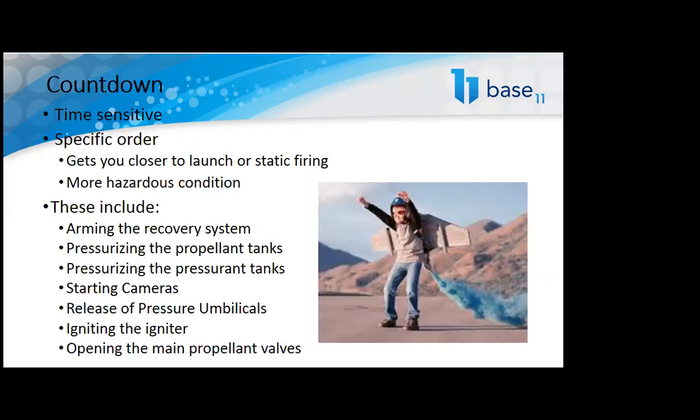You've loaded the propellants. You've loaded liquid oxygen. Now you're in a hurry because the liquid oxygen is boiling off. So the countdown is time sensitive. It deals with, let's say, you should be able to remotely control the arming of the recovery system, pressurize the propellant tanks, pressurize the pressure tanks, start cameras, release the pressure umbilicals, turn on the igniter, and then open the main valves.